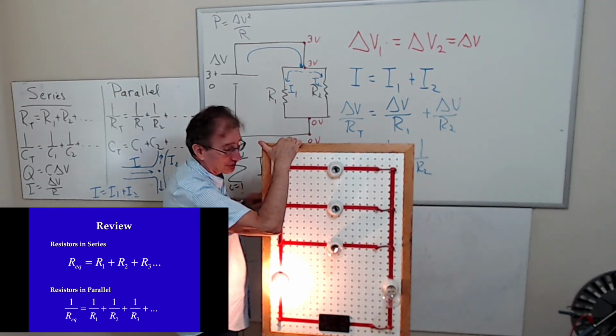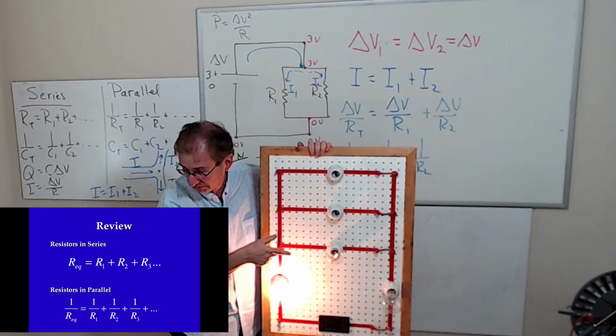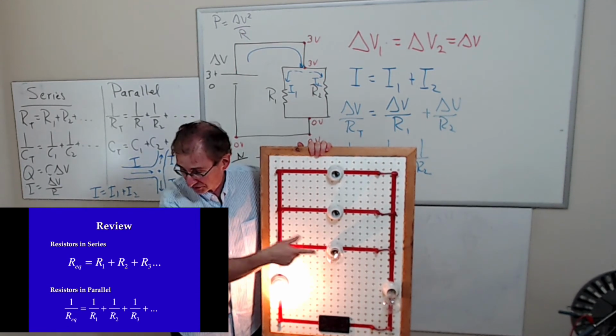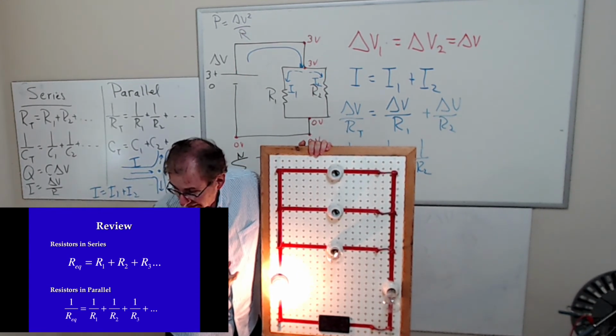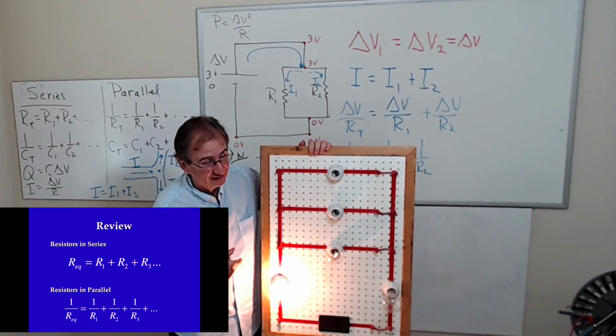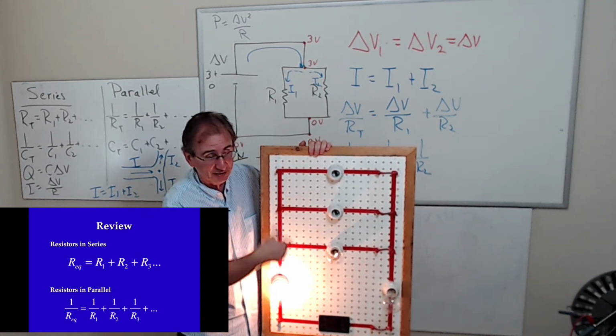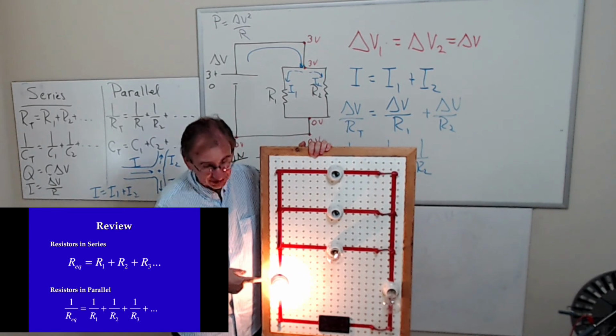they're in series, so how is the current going to be through each one of them? Isn't the current going to be the same through each one of them, since they're in series? And since they all have the same current, the one with the biggest resistance has the biggest voltage drop, which is this one.